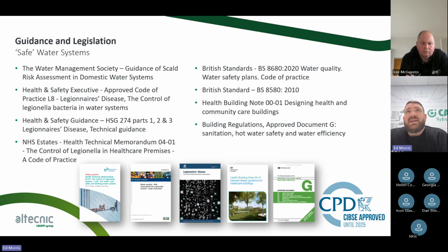So some of the guidance and the legislation that sits around it, there's plenty out there. There's lots of documents that you can refer to, that you can read up on, that you can gain your guidance from. So things like the Water Management Society, that's the guidance of scald risk assessment and domestic water systems. The Health and Safety Executive, the HSE, that's the approved code of practice L8, that's the Legionnaires' disease, the control of Legionella bacteria in water systems. The Health and Safety Guidance of HSG 274, parts 1, 2, and 3. That's Legionnaires' disease, that's technical guidance.